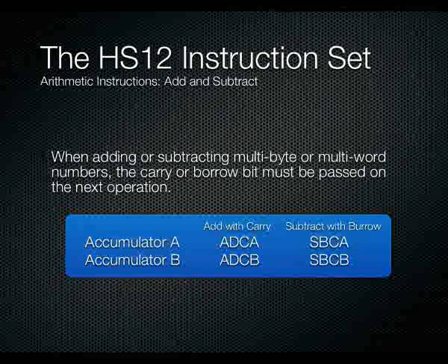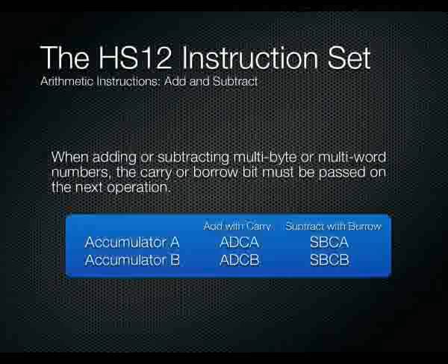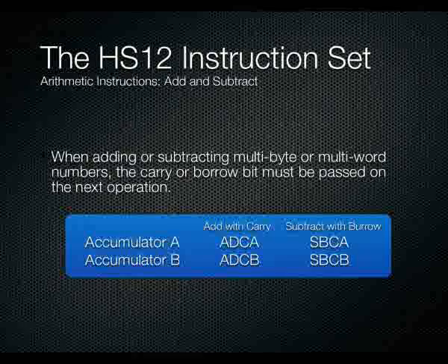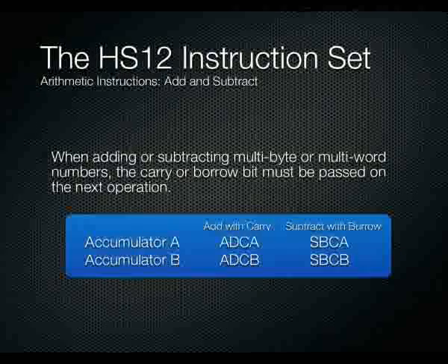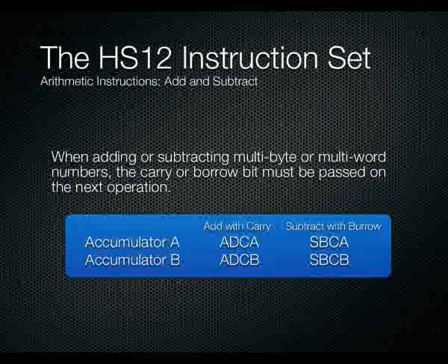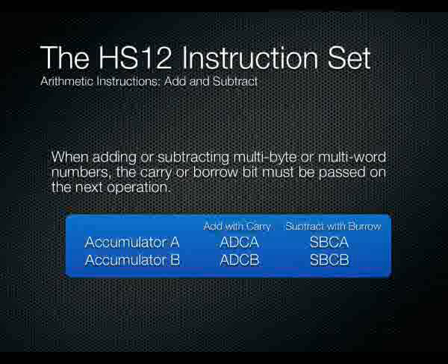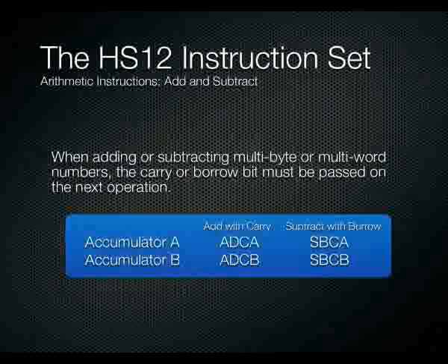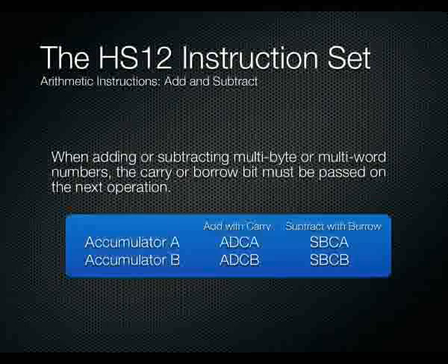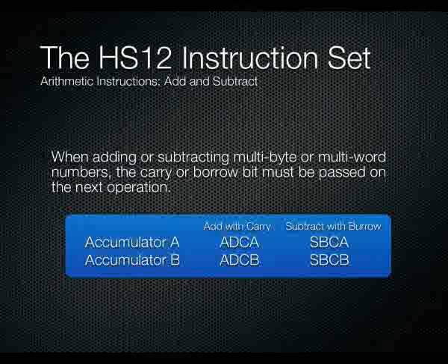So if the carry bit in the condition code register is set, then it will simply add 1 onto the summation. If the carry bit inside the condition code register is actually 0, then of course it's plus 0. So this is good for instructions for doing multi-word addition.